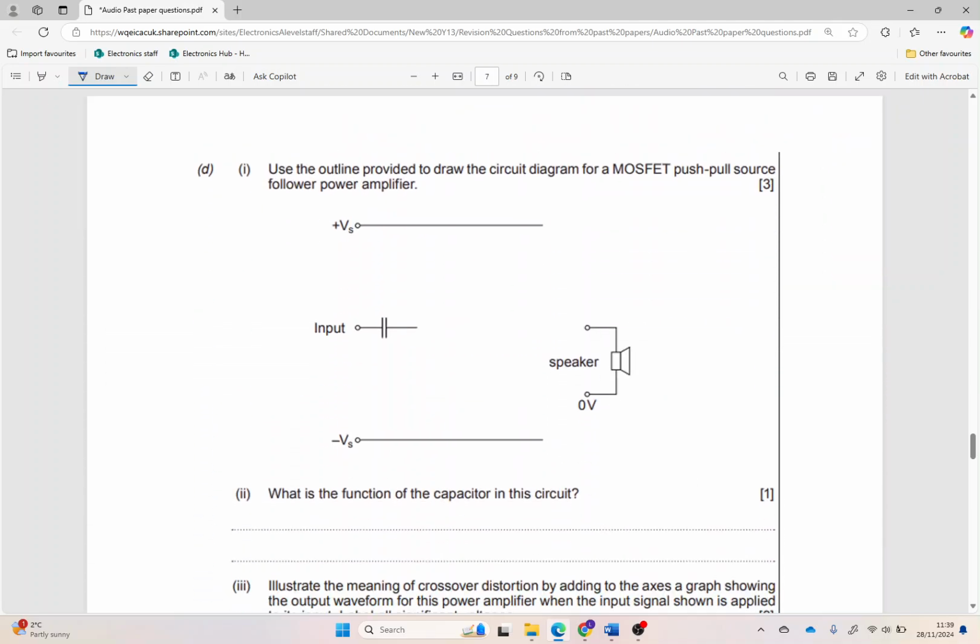Right, okay, so to improve our circuit, we can use a push-pull configuration. I thought this was different because it has MOSFETs, and we don't often get to draw a MOSFET. First of all, I'm going to draw an N-channel MOSFET. On an N-channel MOSFET, we need to put an arrow going in, like so, and there we have it going down to there. And then we need to draw our P-channel MOSFET.